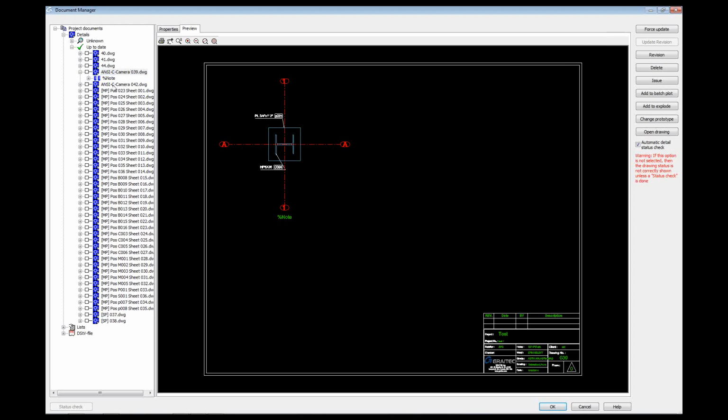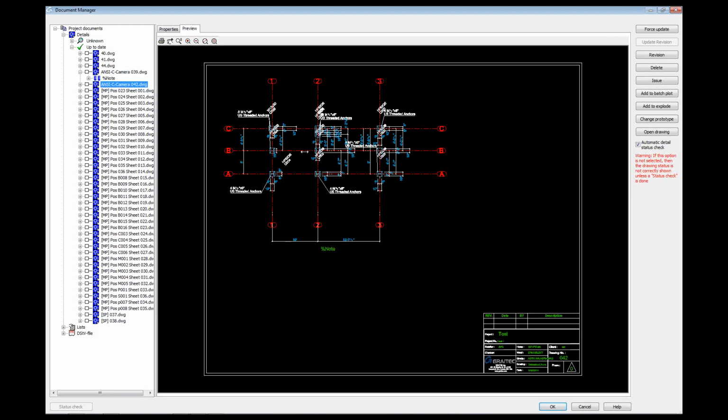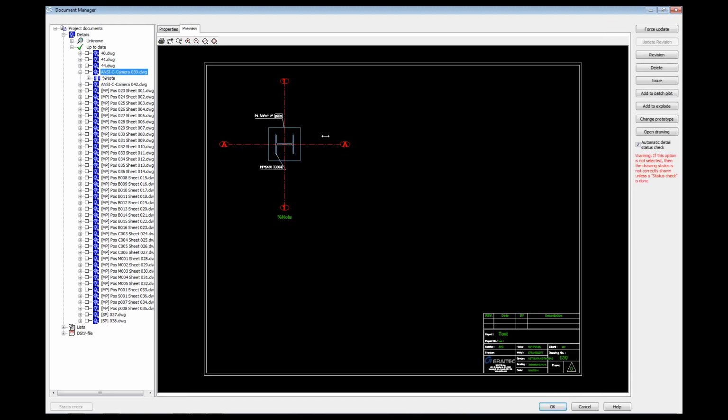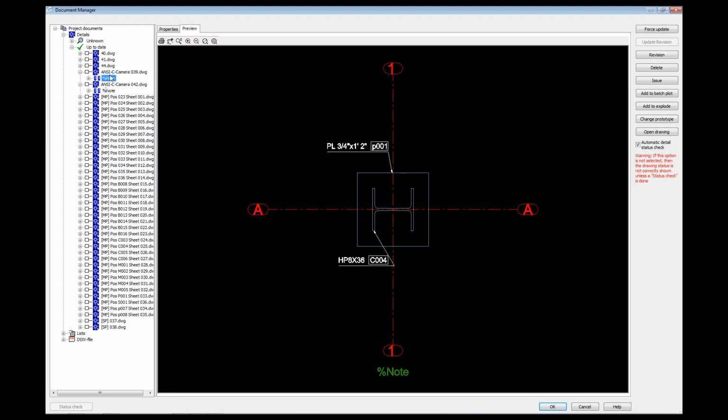Now, for example, what I was saying, Tony, this is his anchor plan, and he wants to put this detail on this sheet, right? So you only have to click on this view here, this little plus, and take this note. If you had a lot more than one detail on this sheet, you will have note 1, note 2, note 3. So views are called notes. Yeah, 100% notes. When you click on one, it will just zoom on that particular detail.